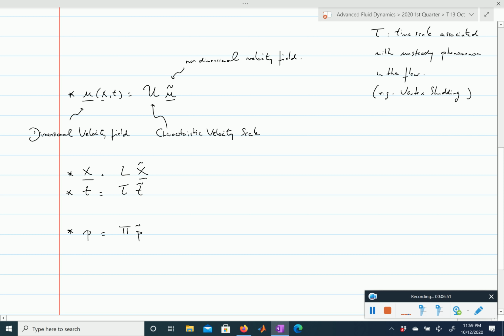And that is because pressure is really the stress, we discussed that, it's the stress inside of a fluid, inside of a flow, which will develop to oppose the change of volume of a material element. Right? And therefore, pressure really reacts to the dominant forces. So if you have a force which is driven by inertia, pressure will be reacting to inertia. If you have a flow which is dominated by viscosity, it could be that really what causes the pressure is a response to the viscosity which is trying to change the volume of a material element.